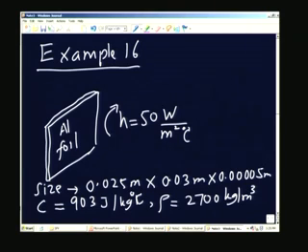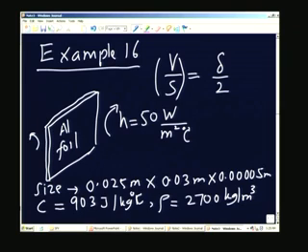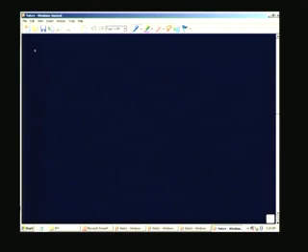If you remember what we have discussed earlier, the volume to surface ratio, assuming that it is losing heat from both sides, is nothing but delta by 2, where delta is the thickness of the foil. Okay, half the foil thickness is the volume to surface area ratio. What I would like to calculate, there are three things which I am going to do. One is I will calculate first the time constant tau,